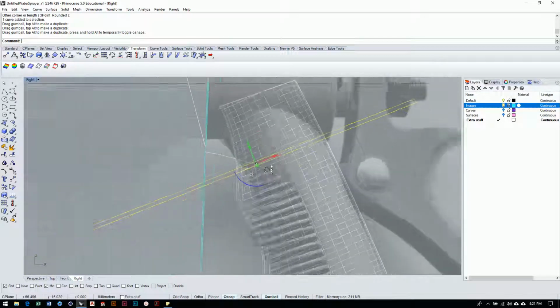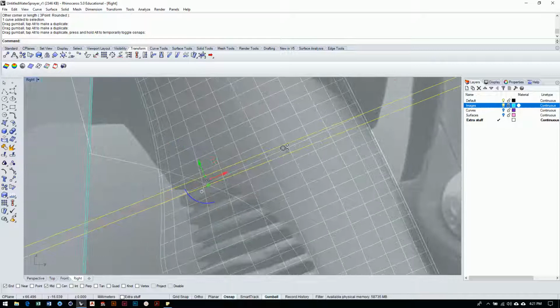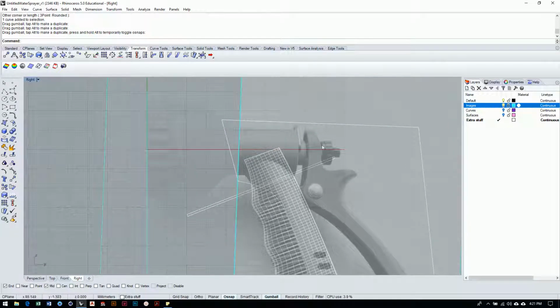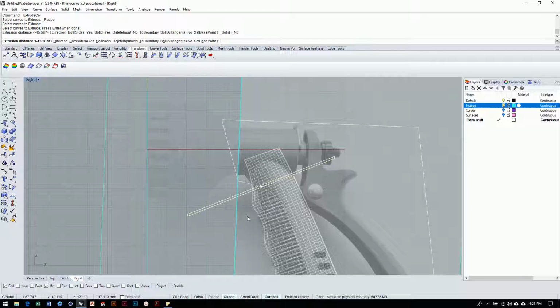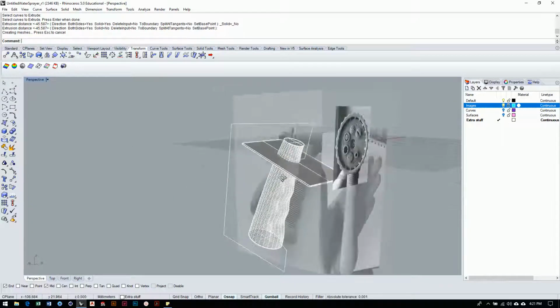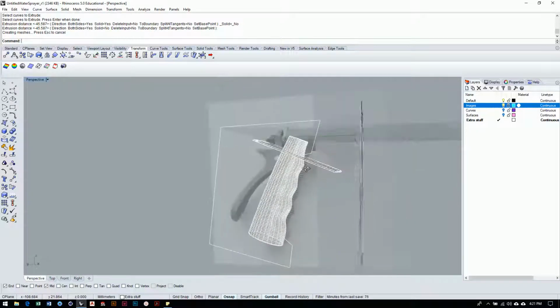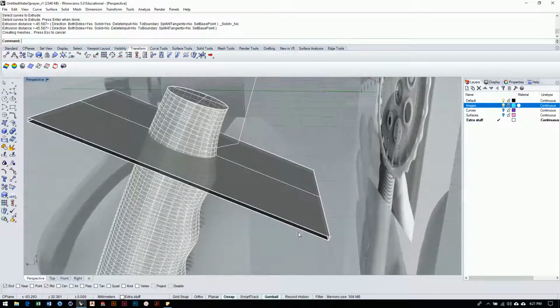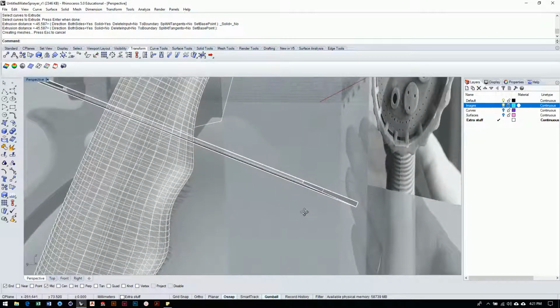And go right in here and just line it up with the very first cut. Make sure it's long enough that it overlaps into this enclosed form we just drew, and it sticks out quite a bit too. Go to extrude straight, grab this rectangle, and in perspective view you can do this. It's probably easier. Just extrude out a surface that cuts through both sides of the model, but make sure that when you do that extrusion, you do a solid extrusion.